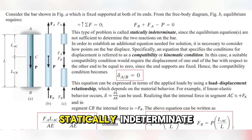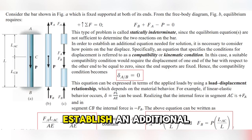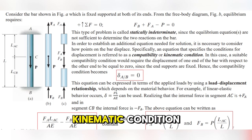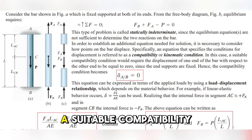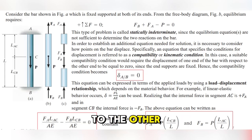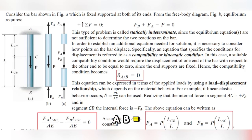This type of problem is called statically indeterminate, since the equilibrium equations are not sufficient to determine the two reactions on the bar. In order to establish an additional equation needed for solution, it is necessary to consider how points on the bar displace. Specifically, an equation that specifies the conditions for displacement is referred to as a compatibility or kinematic condition. In this case, a suitable compatibility condition would require the displacement of one end of the bar with respect to the other end to be equal to 0, since the end supports are fixed. Hence, the compatibility condition becomes δ_A/B = 0.